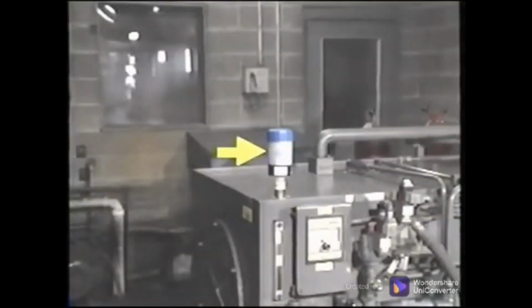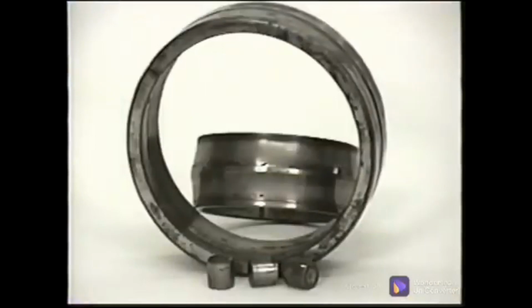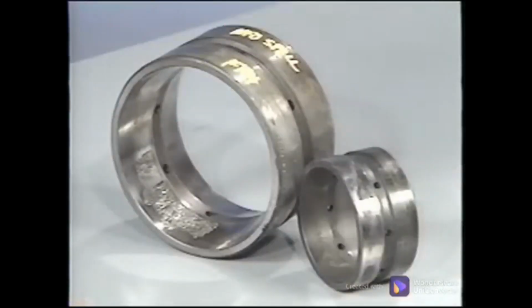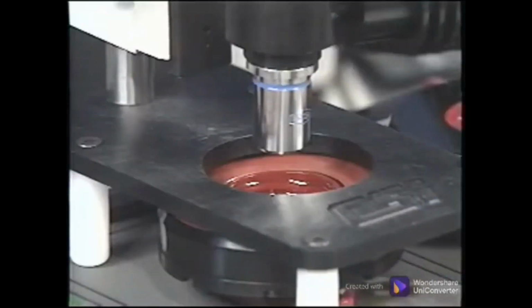Check the breather for possible influx of contaminants and make sure the filter is adequate for the application. Fatigue wear occurs when components have been flexed due to repeated changes in loading and they simply come apart. The root cause may be misalignment or unbalance, but the extra load placed on bearings, shafts, and other components causes separation in the metals. This is the spalling that occurs in bearings or gears, and when examined under a microscope, will be chunky in shape.